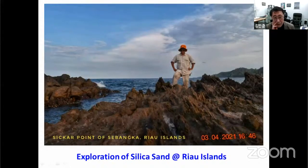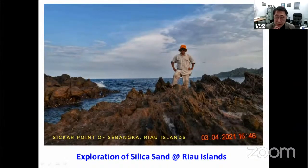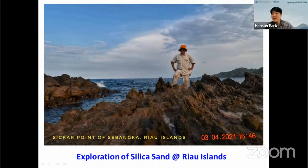As an additional comment, from my experience, to identify and locate paleo rivers, I think you need at least a sparker seismic survey system. The single channel SBP sub-bottom profiler is very weak at generating strong pulses of seismic energy. Okay, thank you. I assume the sedimentation rate is quite high around Indonesia and the Sunda Shelf. Yes, so you must see the deeper part of the sedimentary structure, and you should use at least the sparker source type.